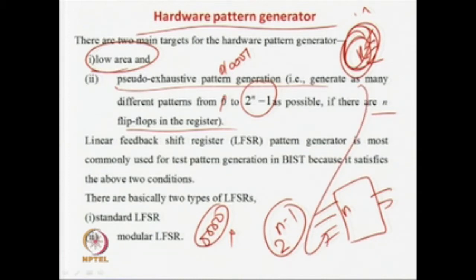And if you want to apply these in a specific order like K1, K2, K3, K4, which are among those k test patterns, you require a very sophisticated circuit. For example, the initial pattern is say 00001, then 1111, then 00010, something like this. If you want to generate these 3 patterns which are your test patterns, you can implement it using a sequential circuit, a 4-bit register and some combinational circuits. This is your first output, then your next output, then your next output. You can go for digital circuit design with a state machine, but then you have to go for optimization of the gates and all.